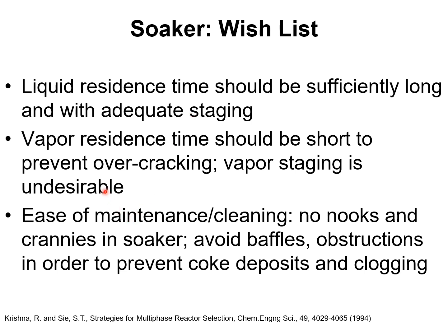Concomitantly, I would suggest that the vapor residence time should be short because the vapor already contains the correct products, and we do not wish to overcrack the vapor. So vapor staging is neither required nor is it desirable.